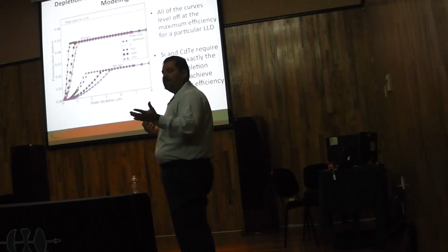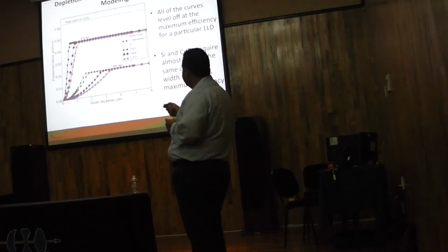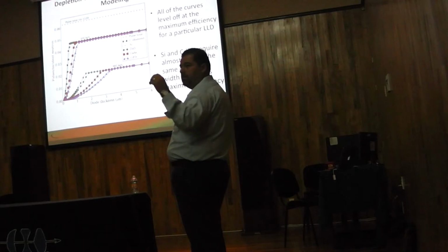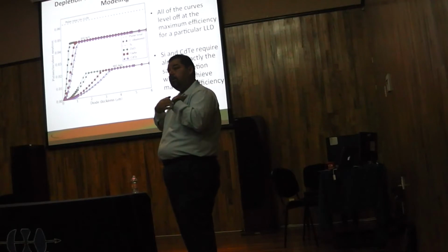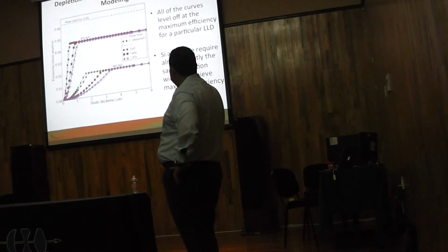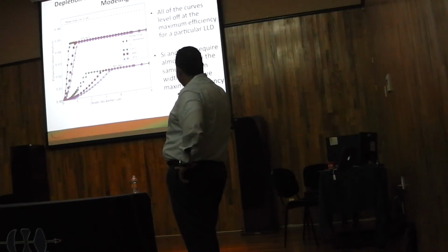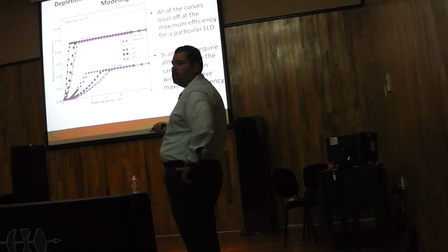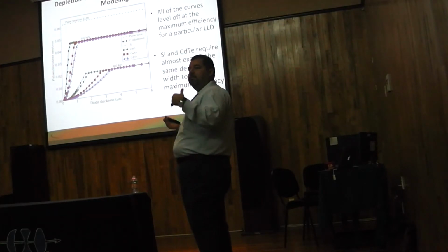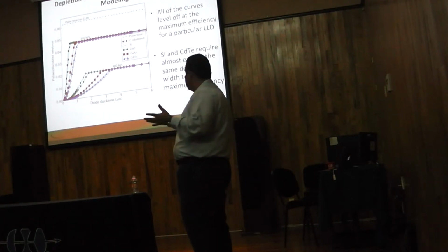So we have to do science before we go and build the device, right? So the science here is we run Monte Carlo simulation. This is the pulse with the signal, and this is the diode thickness. So this is the thickness of the diode that I'm going to use as the sensor. And what we did is we compare silicon with multiple materials. We compare silicon with cadmium telluride. So if we look at the white open symbols with blue, you can see that cadmium telluride is about the same as silicon. So there is no intrinsic benefit of using silicon as compared to cadmium telluride. So we can use simply cadmium telluride.